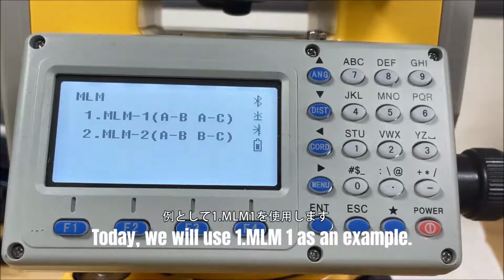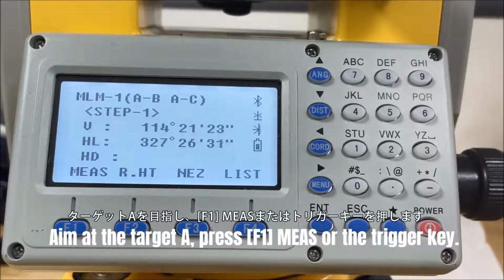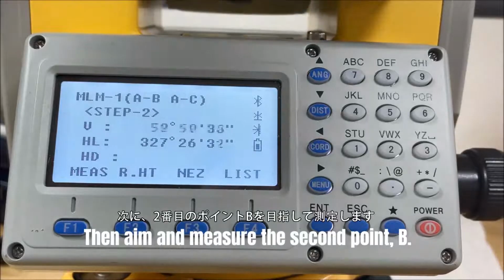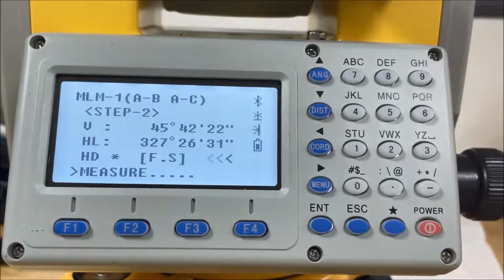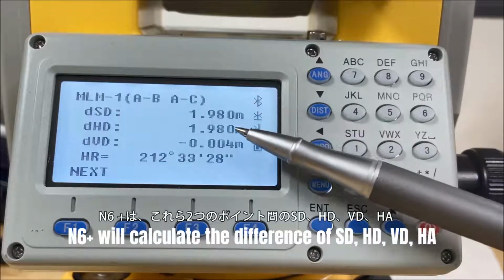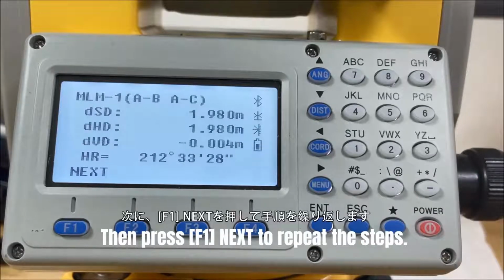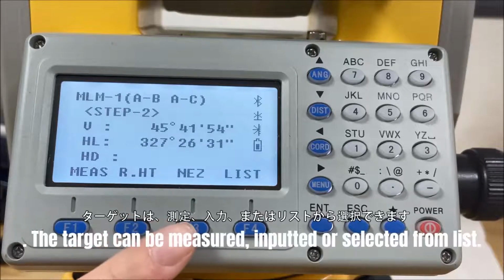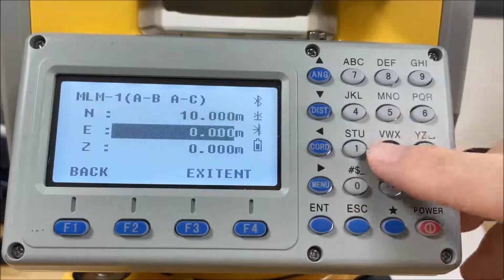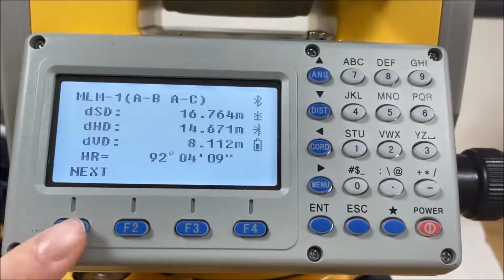Today, we will use MLM1 as an example. Aim at the target A, press F1 measure or the trigger key. Then aim and measure the second point, B. N6 Plus will calculate the difference of slope distance, horizontal distance, vertical distance and angle between those 2 points. Then press F1 next to repeat the steps. The target can be measured, inputted or selected from the data list. In MLM, the result will not be saved.